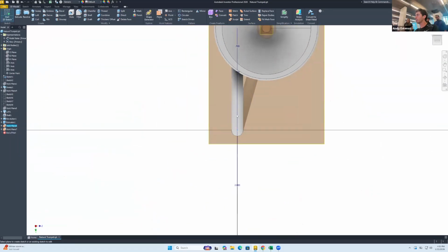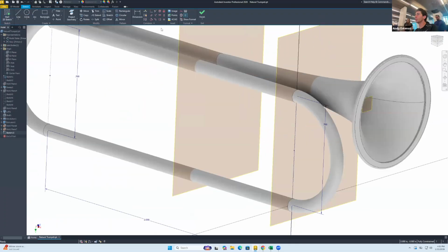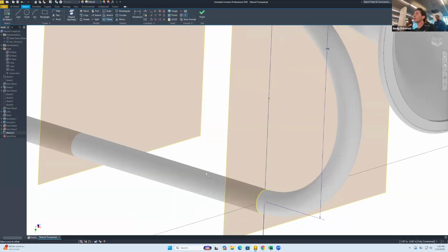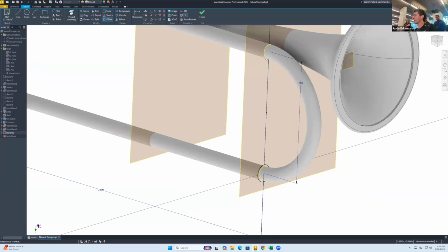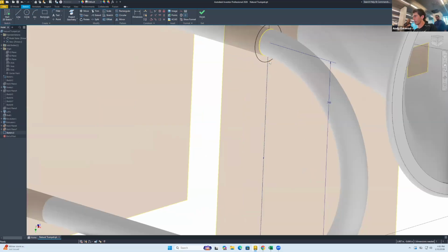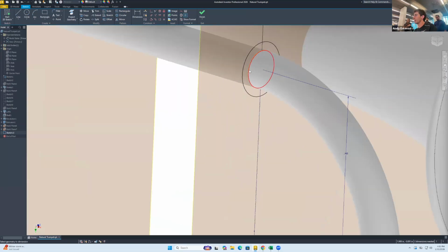So in this portion right there, we'll go here to the sketch. I'm going to click in here. And what we can do is go here to project geometry. We can select that circle. We can select that circle. And we can do a quick offset of this stuff, and another offset in there. What's the button you're using for offset? Oh, this one. Okay, right there. And then no worries. We'll make this 0.015.